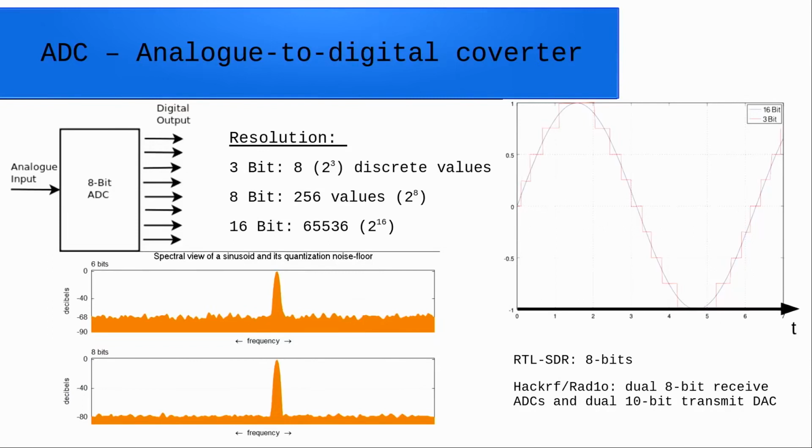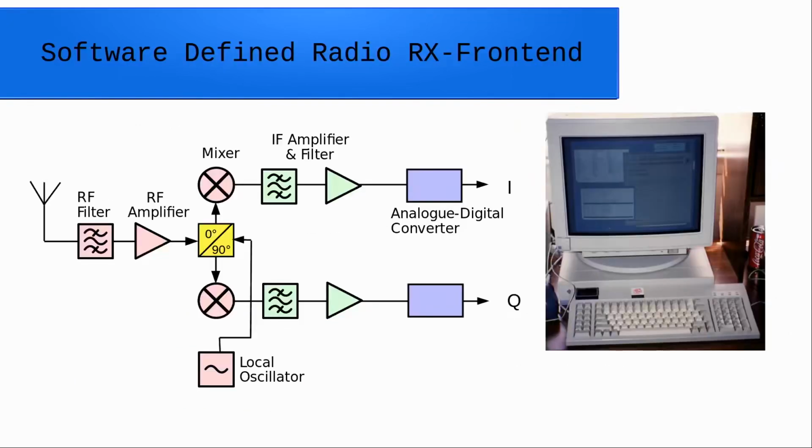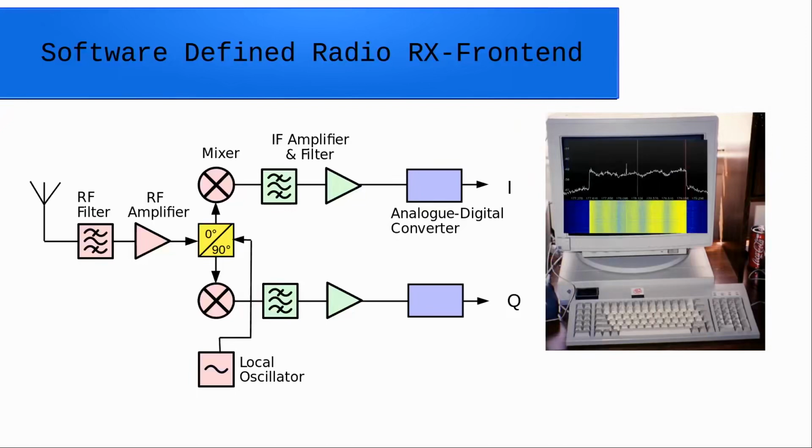What we also see here is, on the right side, our signal in the time domain. On the left side we get the frequency domain. So how do we get the frequency view of our signal? Here, for example, in the form of a spectral view, and down here is this one with the nice colors. This part is called a waterfall diagram.